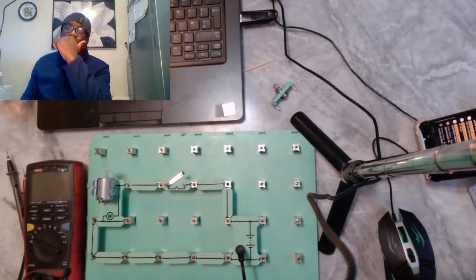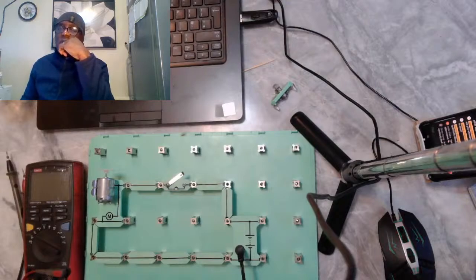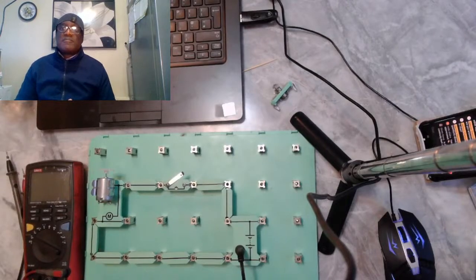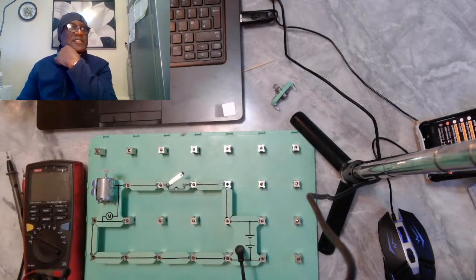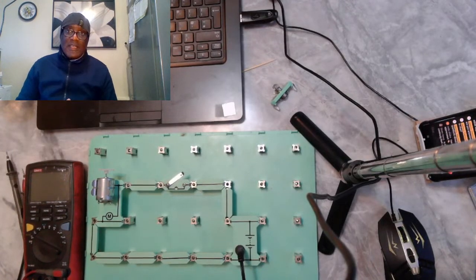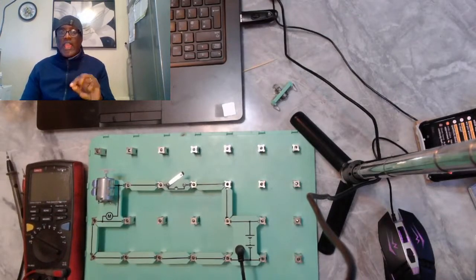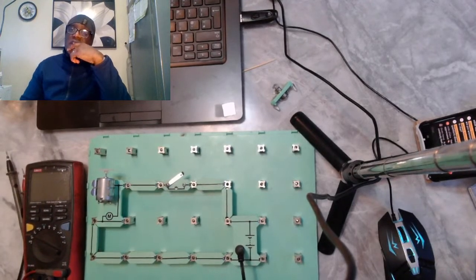But I'll tell you something. Continuity is not always the best way of testing circuits. Can anyone help me on that one? To you all on the live stream here, why is continuity not the best way to test circuits? Voltage drop is the best way, Mr. Given. Voltage drop is the best way of checking for resistance or for an open. You want the circuit to be live, because continuity,